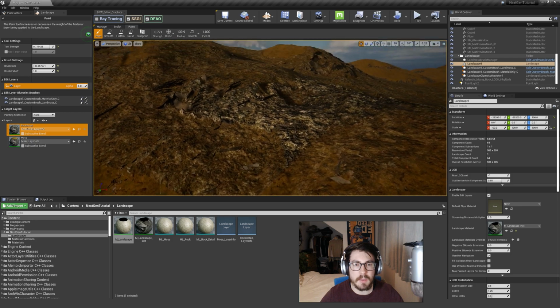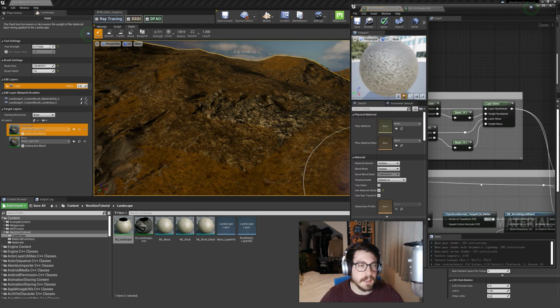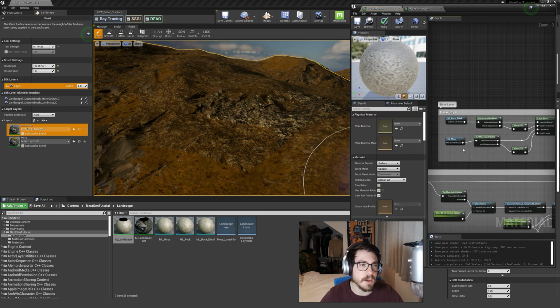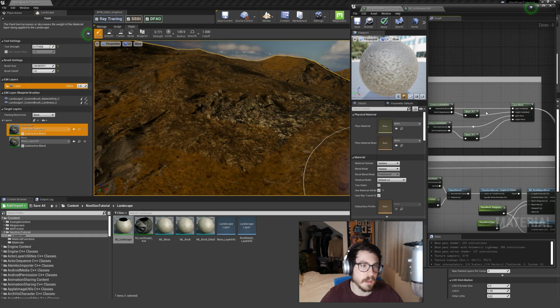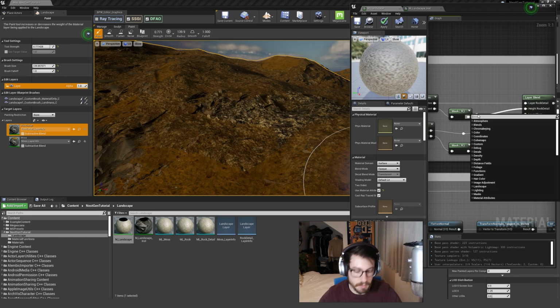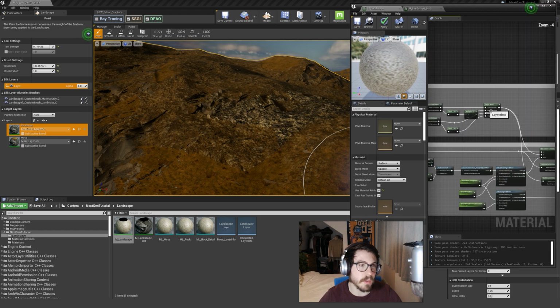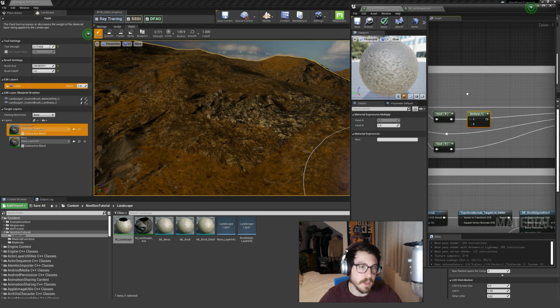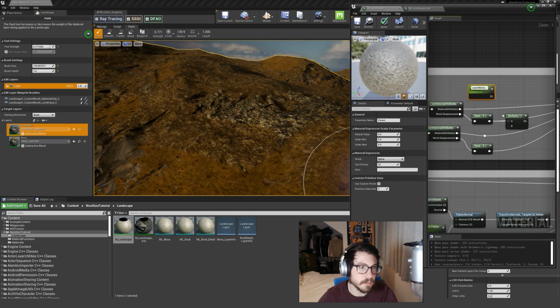materials. I think we can fix that by going into the material again. And then we will need to adjust these masks slightly, the height masks of these textures. And we can do that by multiplying this here to get a bit more control over how we are blending these two together. So I'm just going to call that layer blend, goes with moss strength.